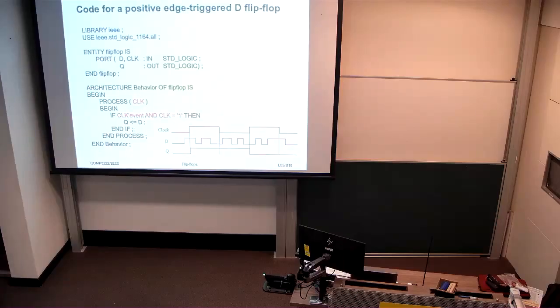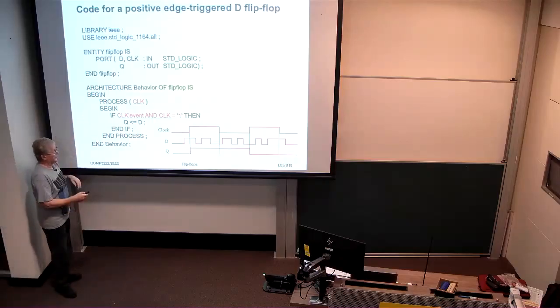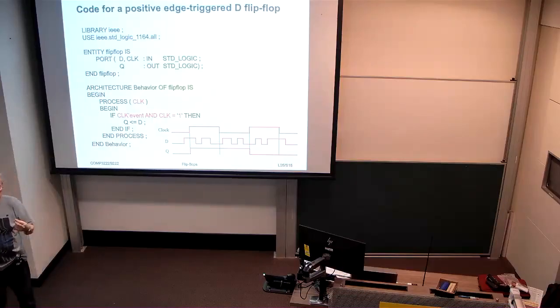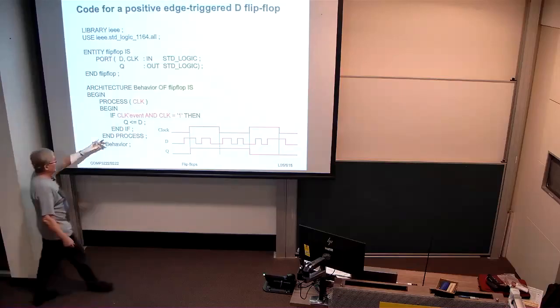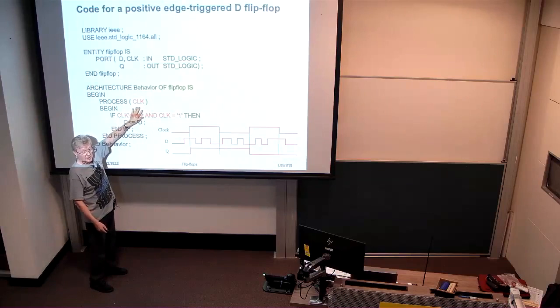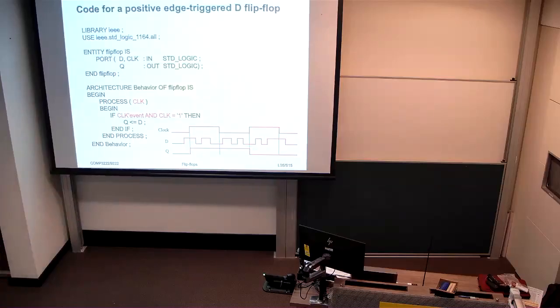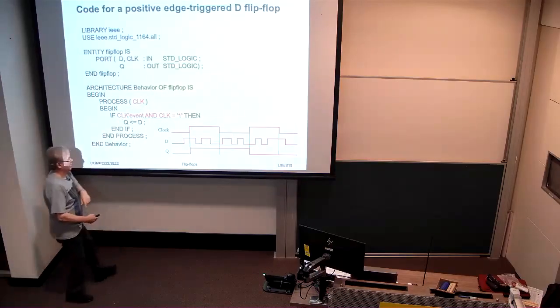Okay. What about a flip-flop? So this is an edge-triggered device. Flip-flops are edge-triggered, latches are level-sensitive. A flip-flop is also called a synchronous element because it's synchronized with the clock. We only ever have the clock in the sensitivity list. That is the only signal you put into the sensitivity list when you're describing a flip-flop. Don't care about the guards, don't care about what other signals you might be putting on the right-hand side of an assignment. Does not matter. The only thing that goes into the sensitivity list is the clock.